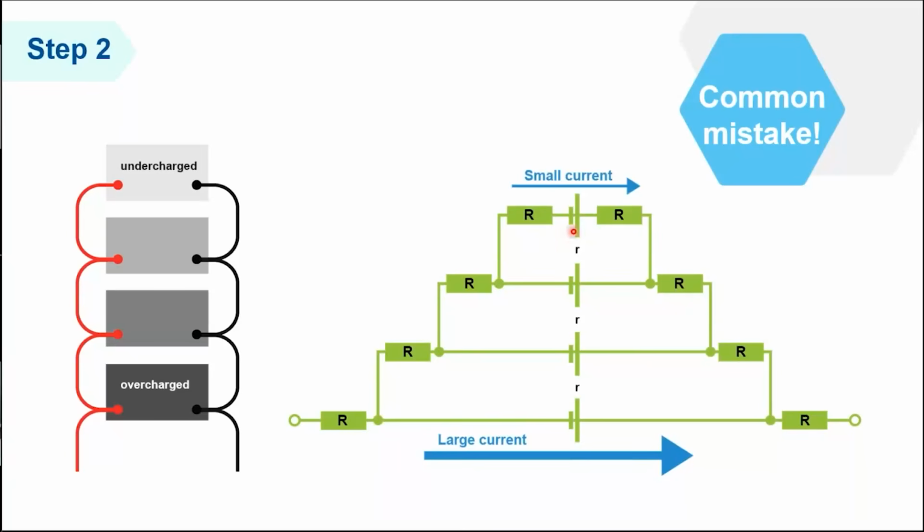And the top battery gets charged with a lower voltage than the bottom battery because there is a voltage loss here until the voltage reaches the higher battery. And the result is that the bottom battery is working harder, discharging harder, and it will fail very soon.